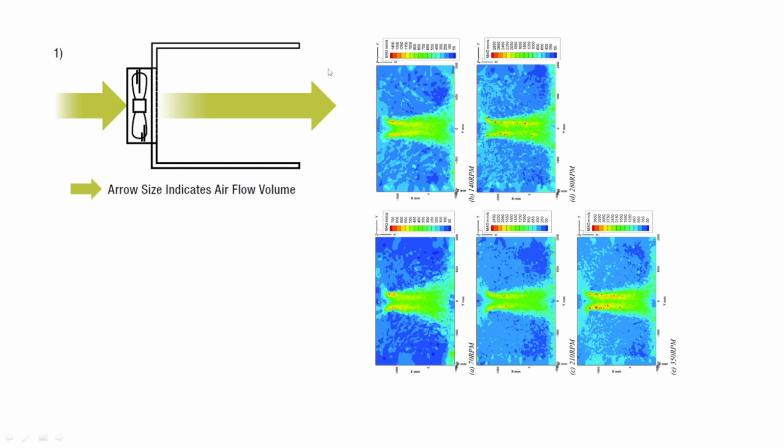There are a couple of flaws with my CFM test apparatus. The first and foremost is my tube is too short. So when I put my anemometer in, it fills up a large portion of the back area and creates some back pressure. So it's not a true open airflow environment. It's sort of halfway between looking at an air cooler and an open airflow environment, causing back pressure. That is a disadvantage with my testing.